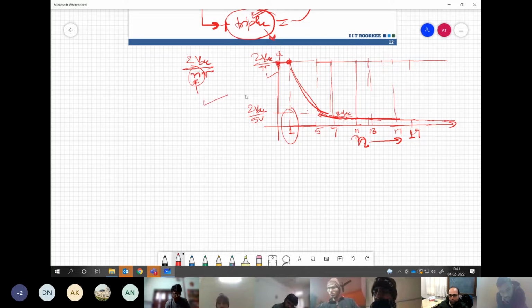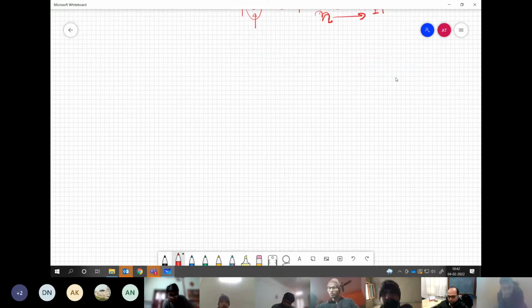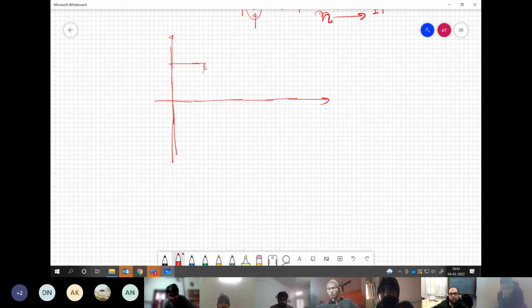Now we have seen that when we are having a square wave mode of operation, the magnitude of the fundamental is fixed. We cannot do anything about it. So to have some control over the fundamental, we introduced one switching angle in the quarter cycle. We are maintaining all the symmetries in the waveform.